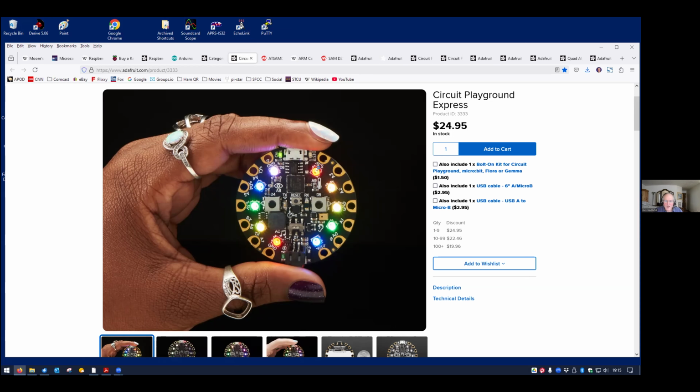What else? One cable connections. Let me talk about this. This is a USB cable. All your development is done with a single USB cable here to your PC that gives the board both power and bi-directional communication. So you can both talk to the board and get things back from the board on that. This down here is a power supply only connector. So once you're off the computer, you can power it with a battery like this. So this is actually an Adafruit battery to one of their devices. And that's just got 3 AAA batteries in it. That's what I use to power it.